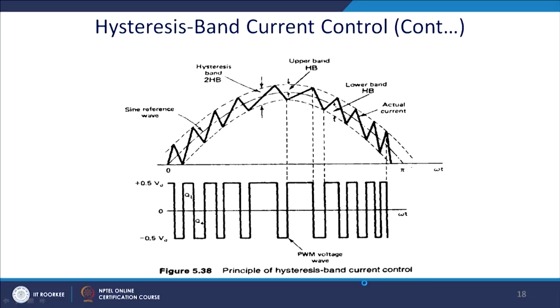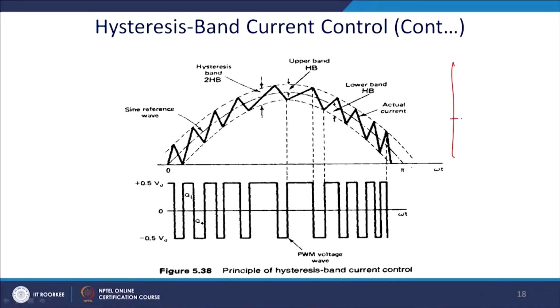There is a different kind of band, the algebraic band PWM. We may also have proportional band PWM. So, this is the sine wave, this is the lower band and this is the upper band. So, let us discuss the constant band PWM, where you can generate a band by an op amp very simply. So, essentially let us consider a 2-level inverter.